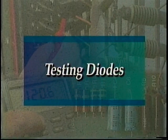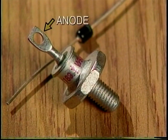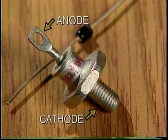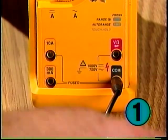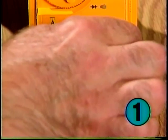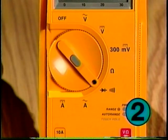Testing diodes. A diode is an electronic device that allows current to flow in only one direction. A diode has an anode and a cathode. To test a diode, apply the procedure. 1. Connect the test leads to the meter. 2. Set the meter to diode test.